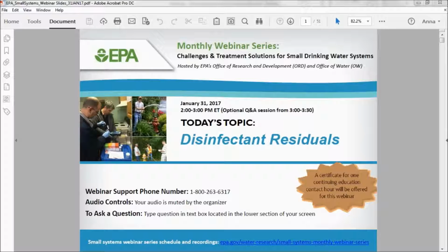But what I would recommend doing after you analyze the sample, if you can analyze the pH of the sample with the DPD reagent in it, it should still be within the 6 to 7 range if it was adequately buffered. If you've exceeded that buffering capacity, you'll have a higher pH.